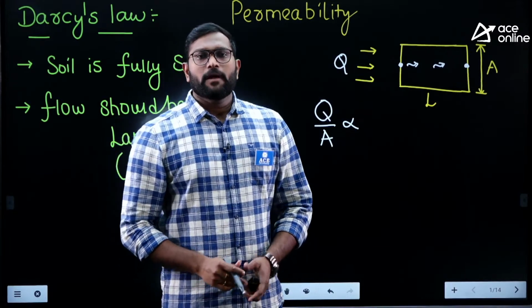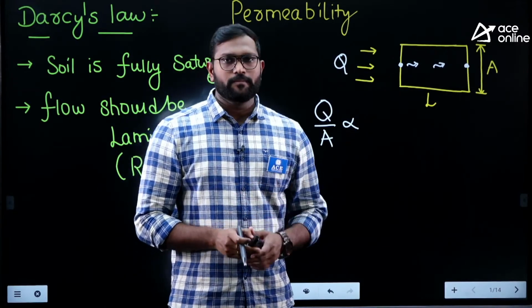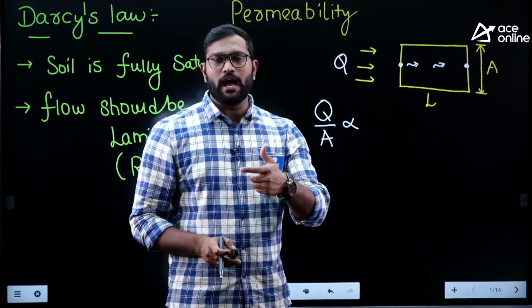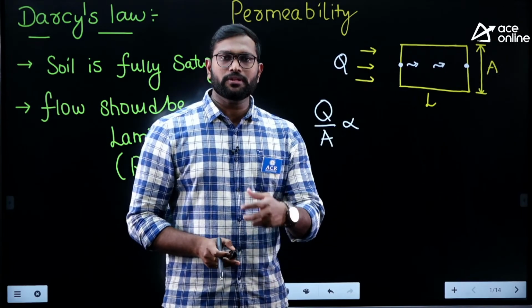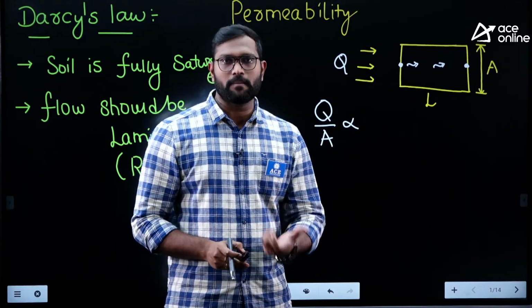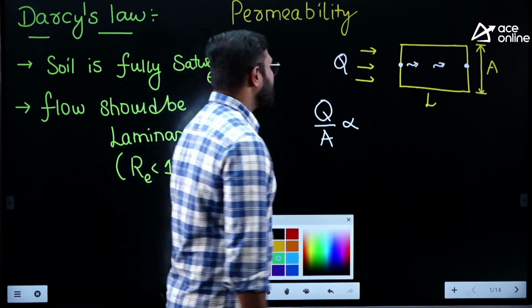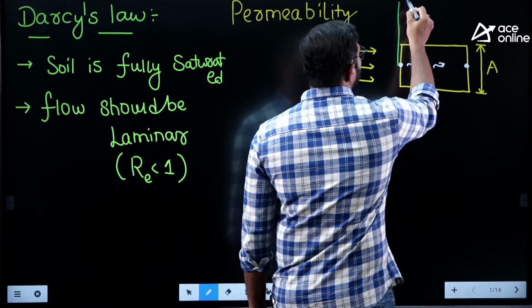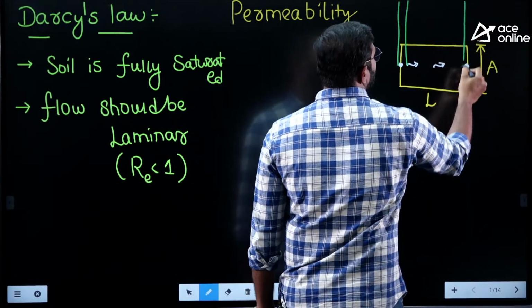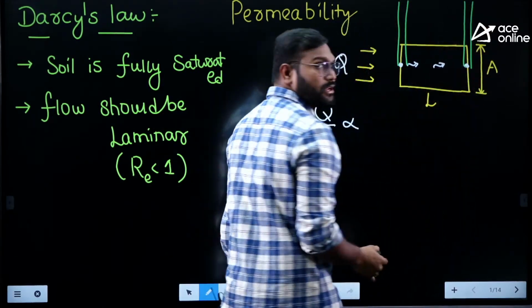You know that when the flow is passing through the soil, the surface of the solid offers resistance. Due to that frictional resistance, we can see some losses. How are you going to measure those losses, sir? If we insert a piezometer at both levels, it shows the water level.